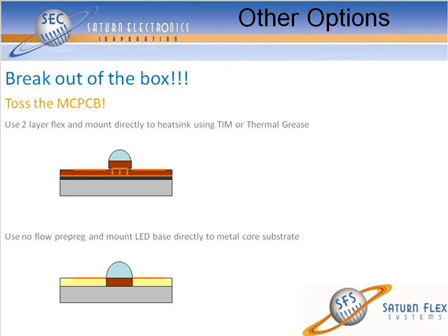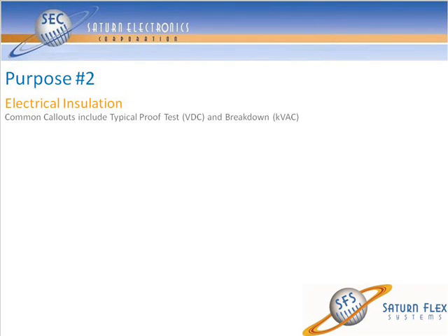In electrical insulation, there are so many ways. I'm not even going to get into it, because it's been covered quite a few times. But I think they made a great point yesterday. Consider your UL needs. I've been in a couple of situations where they're doing their UL roll-up and the material they called out didn't meet their voltage insulation requirements for UL. So again, be cognizant of that. Check into all of these factors before doing your build.